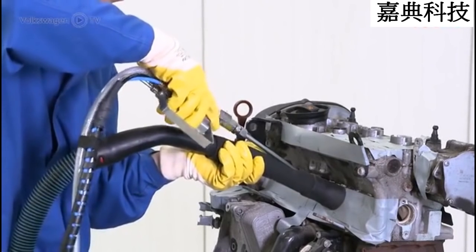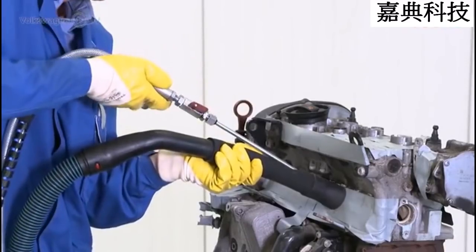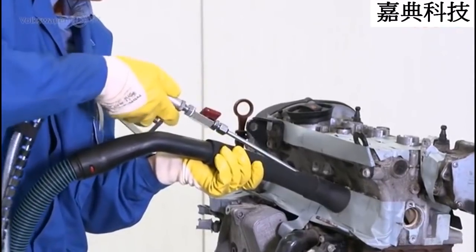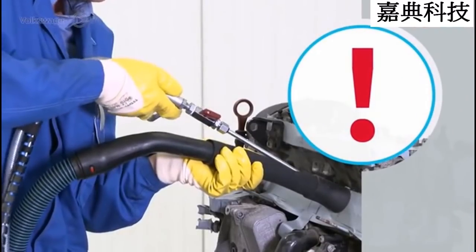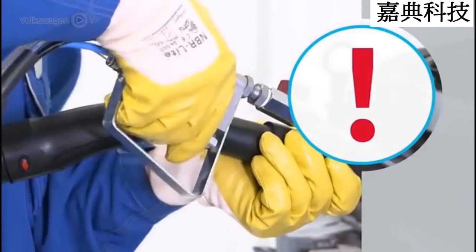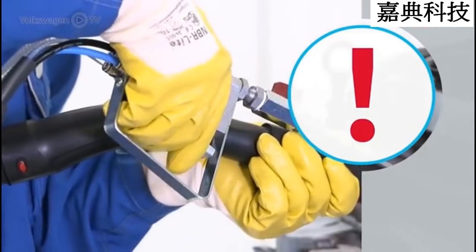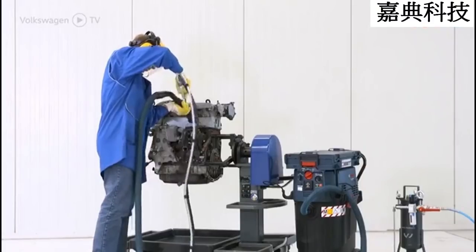Experience has shown that the best way to loosen the coking is to make a semicircular movement around the valve. For optimal results, granulate blasting should be carried out for 2 to 3 seconds alternately with pure compressed air. This prevents a backlog of the granulate.